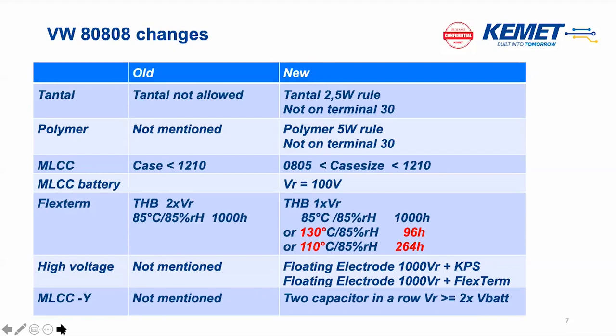Then they have this extreme flex term testing that we had in the past. We weren't really able to offer a broad range of capacitance values because this 2 times rated voltage acceleration was a big roadblock. Nobody, even the other, bigger suppliers, at least the Japanese, was really sure how to handle that, because the maximum we typically test is 1.32 times, but not 2 times.